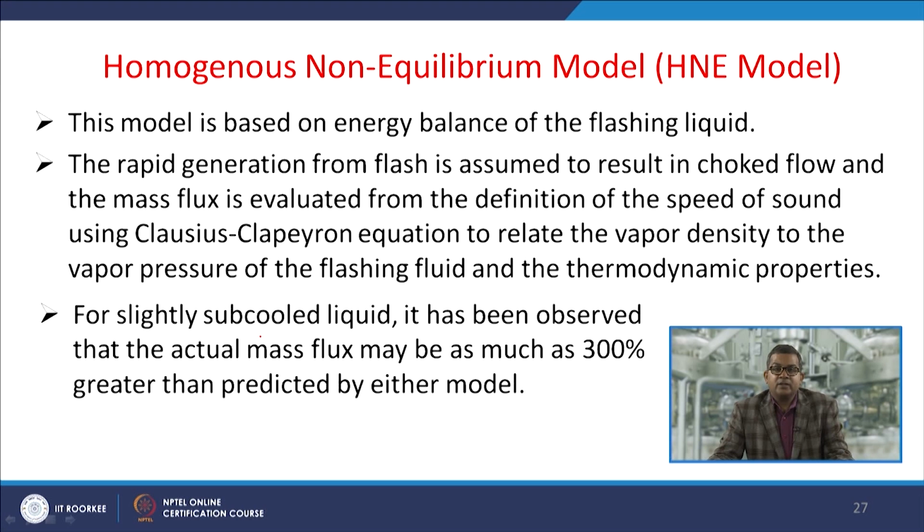For slightly subcooled liquid, it has been observed that the actual mass flux may be as much as 300% greater than that predicted by any of the models which we have discussed previously.